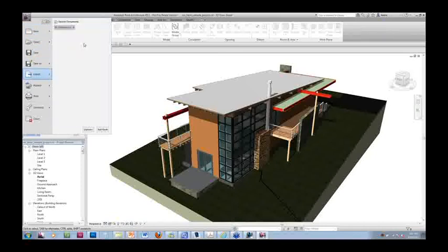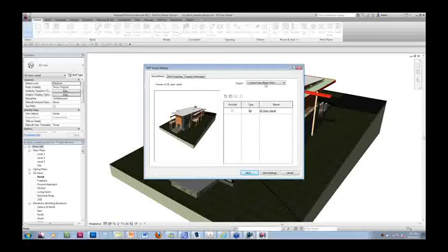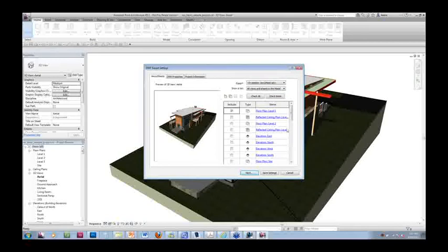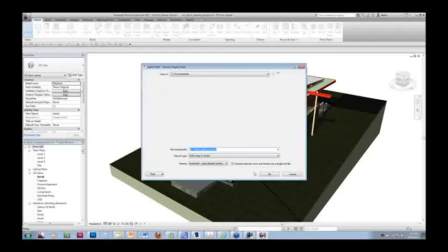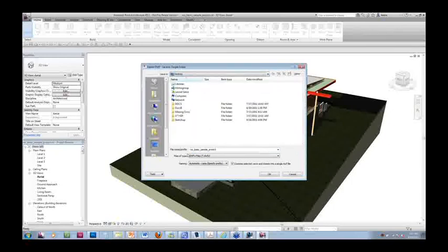So what I'll do is I'll export DWF, and all you need, or whoever's using this, is to select what they want to export. So I'm going to select the first floor. I'm going to select the second floor because it's a 3-story building, including the basement, and I'll make sure I select level 3. And I'm also going to make sure to select the 3D view, and that kind of tracks everything else that is in the plan. So it means even though you're exporting in 3D, you can work on the plan view, and they are kind of linked together. So what I normally do once I pick what I want is I hit next, and I'll save this on my desktop, or whatever the location where you want to save it, and that's it.